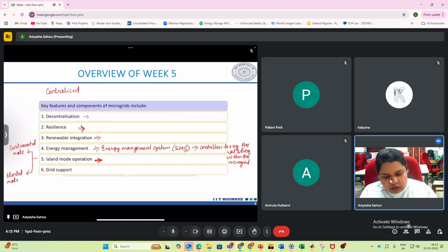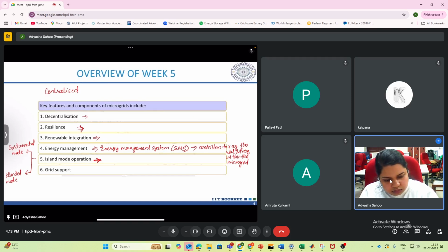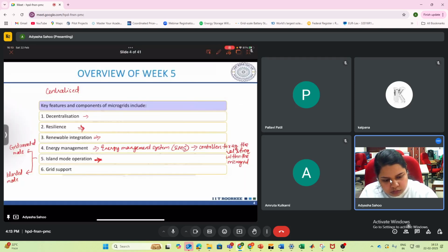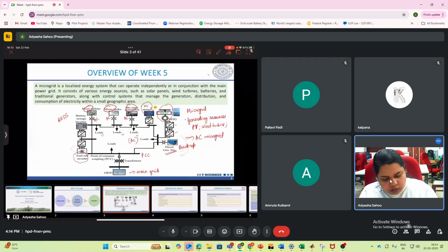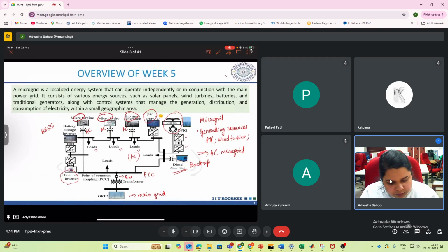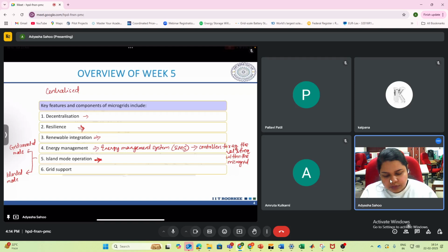that basically, so you see you have a relay here. So if this connection is cut off here, basically if you cut off this feeder or connection, then the microgrid is no longer connected to the main grid, and hence we can say it becomes an islanded grid operation. And then there is a transition phase between these two.